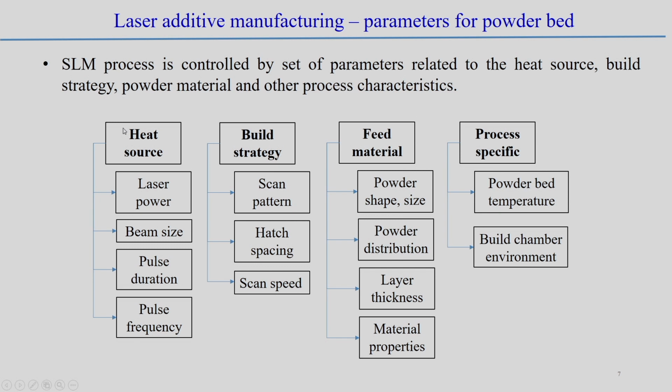Similarly, although we are talking about powder bed based technology, not only this but any additive manufacturing technology is associated with lots of parameters that need to be synchronized at the same time. In other words, optimizing so many parameters in an additive manufacturing process is very difficult, and getting an optimized set of parameters is a huge task. And of course, the optimum parameters may exist only in a narrow domain, not a wide domain where one parameter can vary freely. That normally does not happen in the additive manufacturing process.